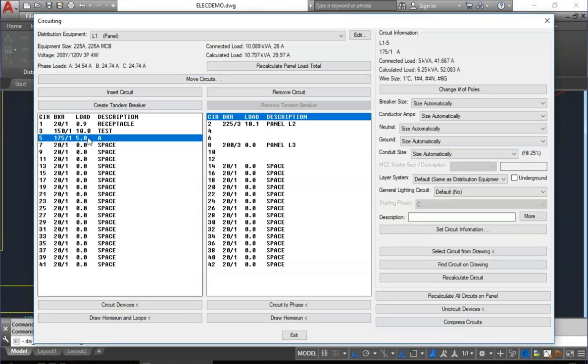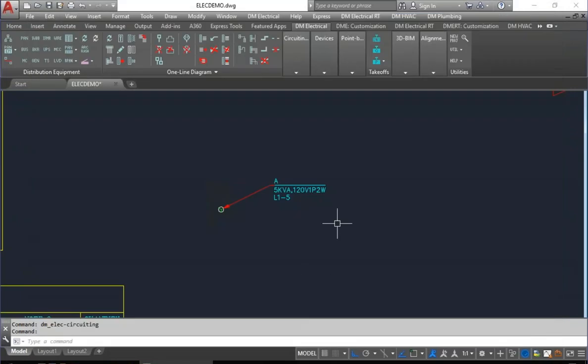So we have a 175 amp breaker, but we do not have a 175 amp wire because it's a motor breaker. It's seen as a motor, and so the assumption is that the motor has protection for the wire as well, so it can actually have a smaller size wire than you would otherwise have. So we have the large breaker, so it can handle the motor inrush, and then the smaller wire. That's how we size the conductors.